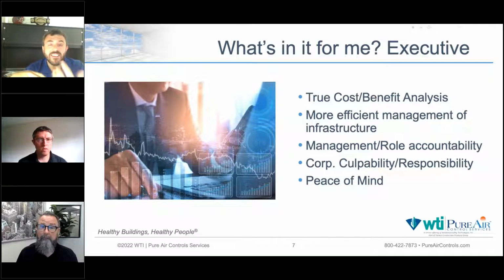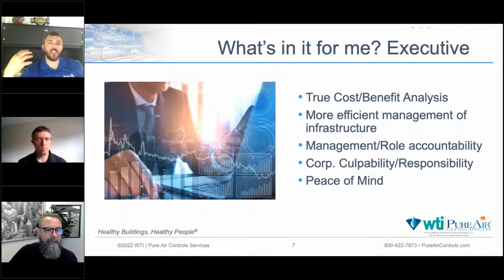What's the physical risk to that area based on the condition of the air handler? Is it in such bad shape that there's actually a physical risk to patients, or is it just a minor comfort issue due to temperature? What's the utilization level of the area served by that air handler? Is it 24/7, or is it 9 to 5, Monday through Friday? How critical is the area generally? Is it off-site, outpatient, or is it an ICU or cath lab or something along those lines?